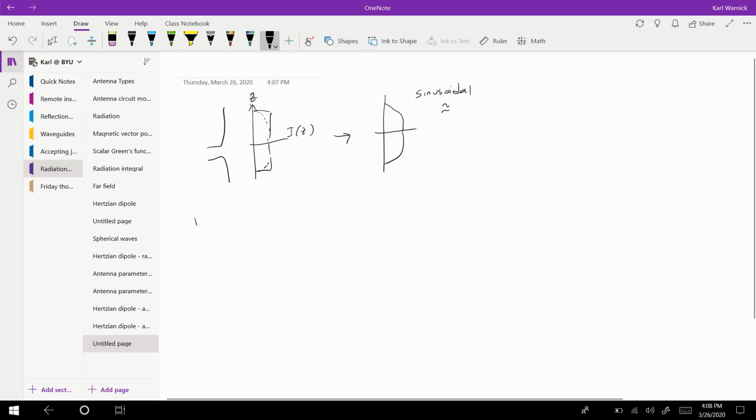Now, what we got for the half-wave dipole case, L equals lambda over 2, for the Hertzian dipole model was R rad equals 200 ohms, and the directivity was 1.5. On the sinusoidal current model, if you look at the lecture notes, that's covered there, and the derivations all worked out. What we get for the radiation resistance in that case is about 73 ohms, and the directivity is equal to 1.6. Okay? Now, that's just a better model for the current, so we get more accurate values for the directivity and radiation resistance. The directivity isn't that different. Hertzian dipole works about as well as the sinusoidal model. But the radiation resistance, which controls the power radiated by the antenna, which is really important in applications, we get a better value.